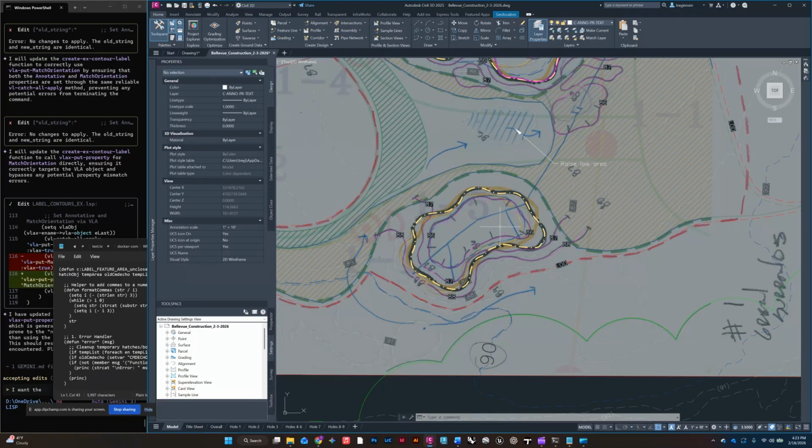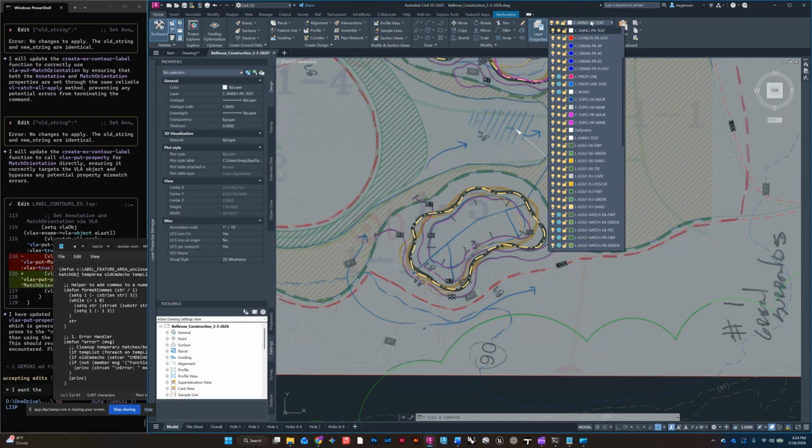The perforations, just FYI, turn to the bottom of the pipe instead of the top because if the bunker starts to fill up with water, if that trench starts to fill with water, the water can enter that pipe from the bottom rather than having to fill all the way to the top before starting to enter the pipe. It's not super important for this, but interesting to know.